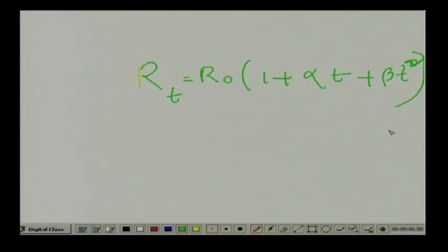In this type of situation I can approximate like this, because higher terms like gamma and all these things will be quite small and can be neglected. So, the amount of nonlinearity introduced by higher order terms will be very little. If I take it up to beta t square, it is more than whatever accuracy we need, as we have seen 0.76% of the full scale. So, it is quite small. Up to second order t square is enough, right.